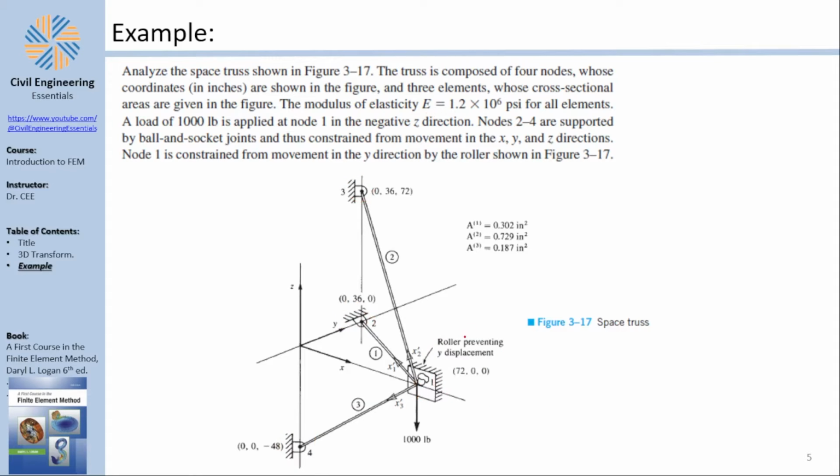Now, here is the thing about this support. This support is a roller faced or resting on the wall behind it. And for a BSc student, that's fair enough. For him, the assumption of a roller means that if you have a roller on the wall, it can carry both tension and compression, because you're assuming that the roller is not going to be detached from the wall.